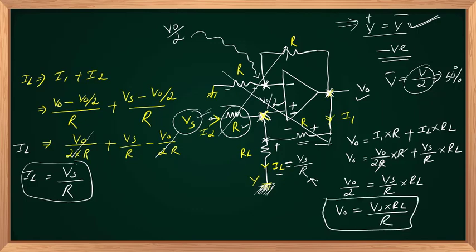So this circuit will produce an output voltage that is equivalent to this and a load current IL that is independent of RL. Its value is nothing but Vs upon R. Right? And always, if these cross products are matching, without doing any analysis, you can directly write the current IL is nothing but equal to Vs upon this resistance R.